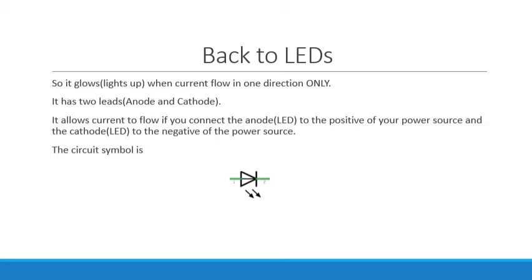Now looking at the symbol below, the circuit symbol of an LED. With the circuit symbol, you can differentiate the anode from the cathode. But note, you can only differentiate it on schematic diagrams. The circuit symbol is what represents an LED on schematic diagrams. You can see where 2 is written. That is where you have the straight line on the head of the triangle. That is your cathode, while the other end where 1 is written is your anode.